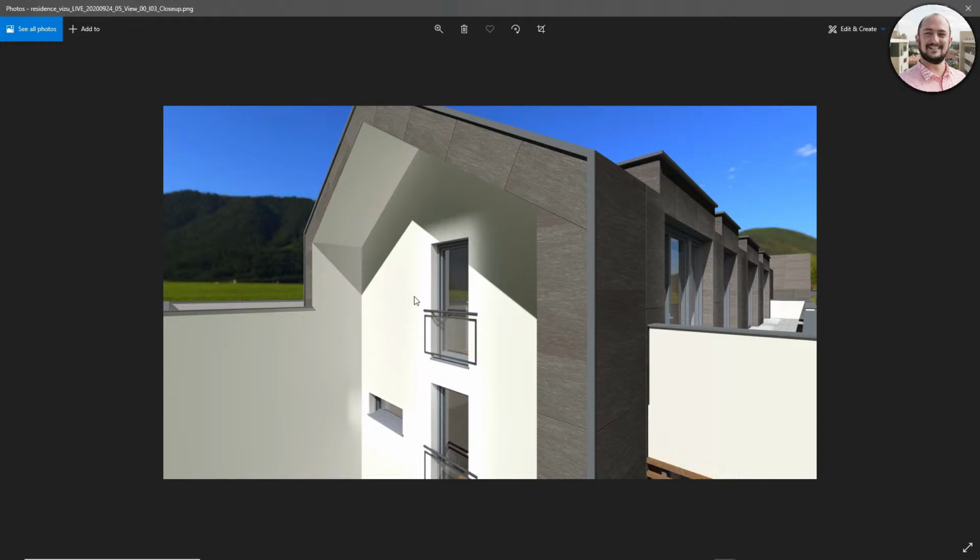And that's the reason why we don't use interior presets for exteriors, because those are tailored for interiors, and those are also focusing on windows and doors for having a better light in the interior. But in exterior scenarios, it is just counterproductive. It's not a good way of approaching an exterior. So that's why we decided to distinguish interiors and exteriors at the level of presets. If you use an interior preset for an exterior, you might end up with a false result because of a halo like this. So don't use that. Use exteriors for the exteriors.